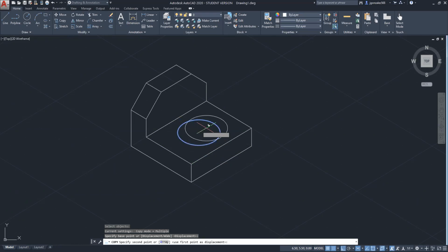All right, so choose a base point at the center, just because that's easier. Now I want you to shift it down vertically 0.5 units. Currently, I have my snaps on, so it's a little difficult. So turn off that one. No, that's not the one. I think it's ortho. Here we go. So 0.5, enter. And that should give me exact. Yeah, there we go, that's the perspective I want. So copy your circle. Make sure that ortho's turned off to make it easier. Shift it from the center point or base point of the middle and go down 0.5.